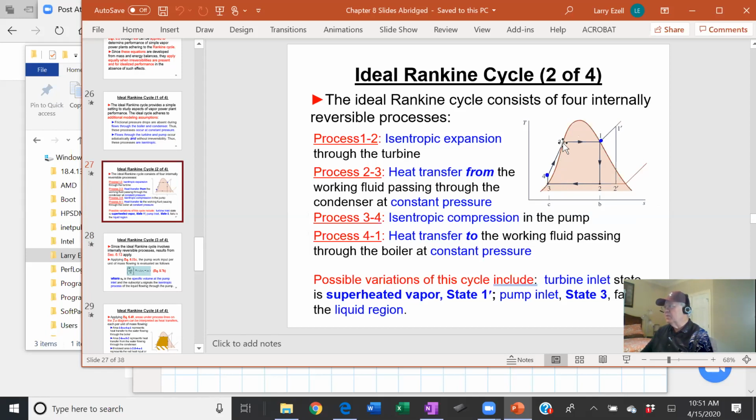This is a saturated liquid. As the boiler starts supplying the heat, the liquid starts vaporizing: high pressure vapor, all vapor, high pressure steam, superheated steam. Now it's ready to go through the turbine. Goes through the turbine as superheated steam, you get a lot of power out of it, drives those blades, and you come out generally as mostly vapor, but some liquid, a mixture, but with a high quality of about 80, 90%.